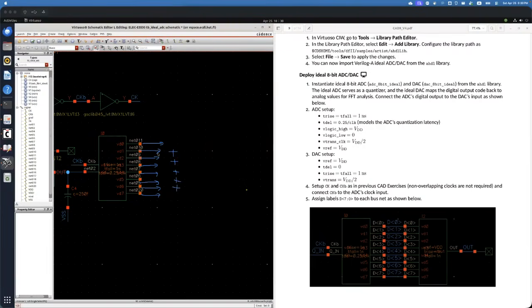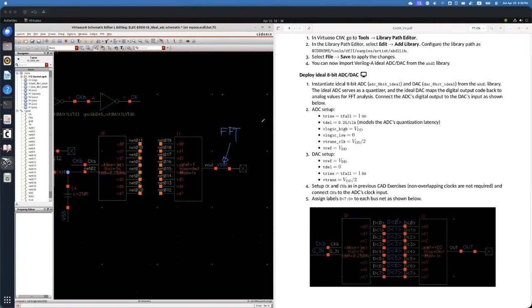Of course, we have to assign binary weights, 2 to the power of 7 and so on down to 2 to the power of 0, and multiply and add them. So it's quite inconvenient. For the sake of simplicity, we can add a DAC, such that we can only plot this one, and then run FFT to verify whether our ADC is working correctly or not.